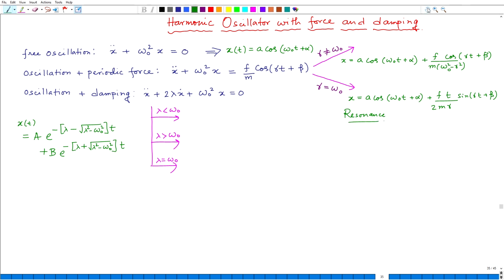Okay. And here you can actually show that again your equation is composed of two parts. One is the complementary function, which looks like a simple harmonic oscillation, plus another sinusoidal, trigonometric oscillatory function with the same frequency and initial phase as that of the periodic force acting on the oscillator, but now it is multiplied or modulated by a linear function t. And you see that there is also a pi by 2 or 90-degree phase shift of this particular integral with respect to the periodic force which is acting on the oscillator. So, that we already have discussed.